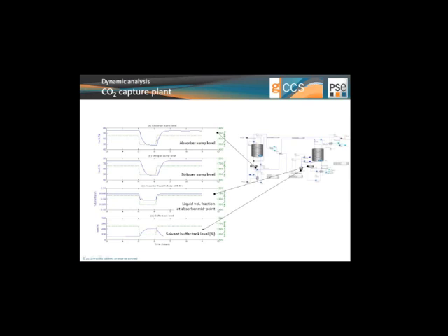And an interesting result was that we obviously didn't provide any control here for the level of this buffer tank. We relax the control for this one. What you can see is that the level increases to what would be in theoretical terms 200% of its actual capacity. What this means is that when we set up this study, we didn't size this buffer tank as we should have. Obviously, this doesn't impact the simulation, it just continues, but in a real system, this would have been a problem. So again, this is something that you need to take into account when you're looking into load changes.